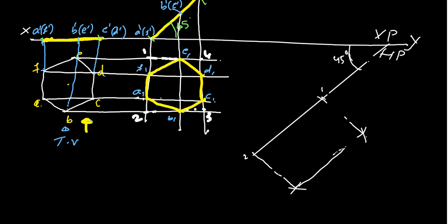Okay, right. After that, what is there between 1 to 2? 1, 2, 3, 4 is here. Between 1 and 2, A and F are there. So now measure the same distance. What is the distance from 2 to A? Mark it on this, 1 to F. Same distance will be here. And what is between 1 to 4? E is there. Measure any one distance and mark on this. Okay, now the total hexagonal will appear on this. This is one of the simplest methods. You can transfer the entire hexagonal from the square.